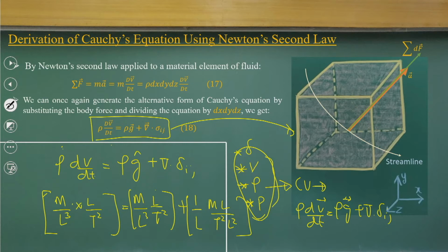So, the basic idea is to demonstrate that all these fields, the velocity field, the density field, the pressure field, the stress fields, all have a functional dependency on space and time for an infinitely small control volume. If I derive it with a Taylor series and the Reynolds transport theorem, finally we will get this form of these equations, nothing else.